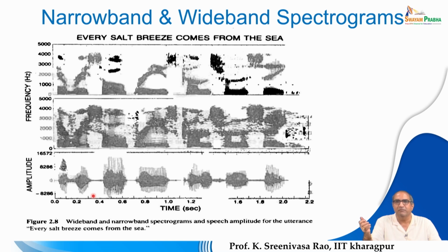Fourier transform is nothing but, by applying a Fourier transform, you are able to visualize that. For that particular 20 millisecond segment, what are the frequency components that are present, and for every frequency component, what is the strength of that particular frequency. Think of a frequency as a sinusoidal signal of that particular frequency. The frequency domain is, for a given time domain signal, if you compute a Fourier transform, then we will come to know the various frequency components that contribute to this particular signal.